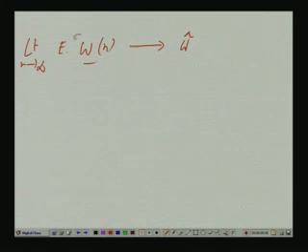But what does converge is the mean of these. So, the filter weights keep dancing, keep changing, keep fluctuating, but as time progresses, the DC value across which each filter tap is fluctuating converges to the corresponding optimal value.